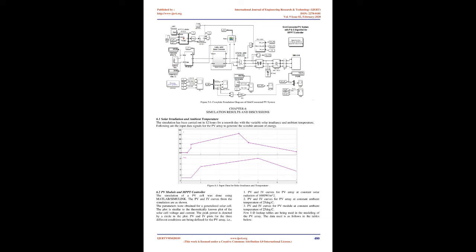Boost converter steps up the input voltage magnitude to a required output voltage magnitude without the use of a transformer. The main components of a boost converter are an inductor, a diode, and a high-frequency switch. These in a coordinated manner supply power to the load at a voltage greater than the input voltage magnitude. The control strategy lies in the manipulation of the duty cycle of the switch which causes the voltage change. Figure 4.3, Circuit diagram of DC-DC boost converter.